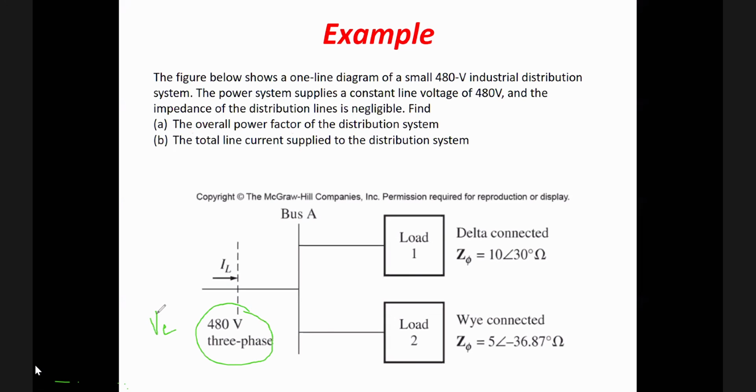This is the main difference. But if I am not given a single line diagram and the question is in written format only, and if I mention any voltage and I don't specify if it is line or phase, it is phase voltage.